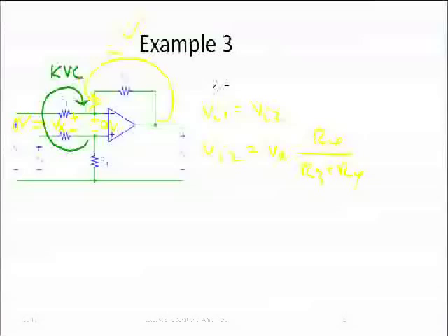Now we still have the other guy here. What's the current I1 flowing into resistor R1? Well, that's the voltage VB minus what is the voltage here at the other side of resistor R1? No, it's not 0. No, not at all. It's Vi1, which happens to be equal to Vi2, and then we have to divide by R1, and there we get current I1.